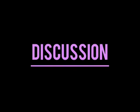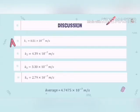Okay, for the outcomes, the coefficient of permeability for our soil sample is first K1 equal to 8.51 times 10 power of minus 7, K2 equal to 4.39 times 10 power of minus 7, then K3 equal to 3.30 times 10 power of minus 7, and K4 equal to 2.79 times 10 power of minus 7.